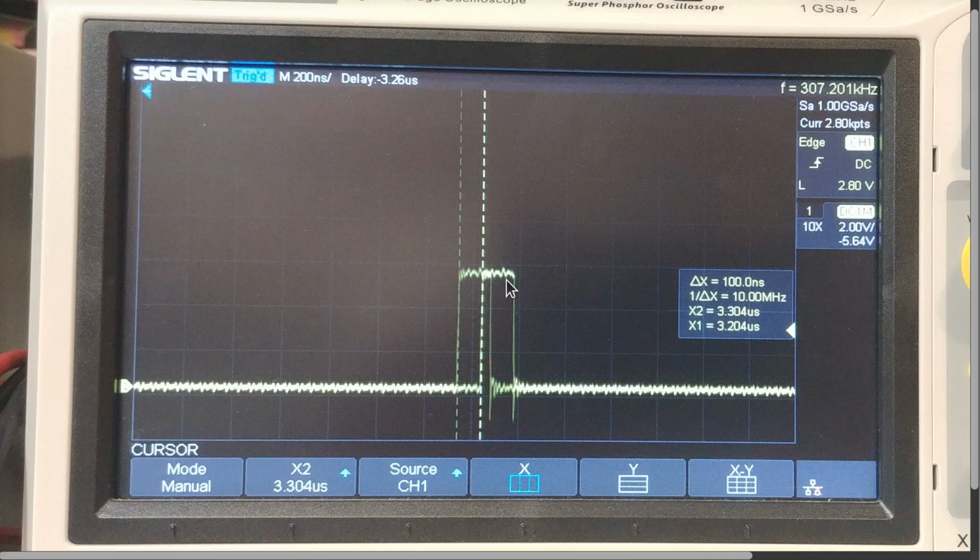The point is you need to understand that it's there, number one. You need to understand whether or not it is a problem in your particular application. Now remember, I'm talking about jitter. I'm not talking about frequency error. If the frequency was off by a significant amount, your bit rate would just be wrong, and the sender and receiver couldn't handle it. In fact, it's generally accepted that about a 2.5% error is as bad as you can get with an RS-232 type communication and still be okay, be legible on the other end, okay?